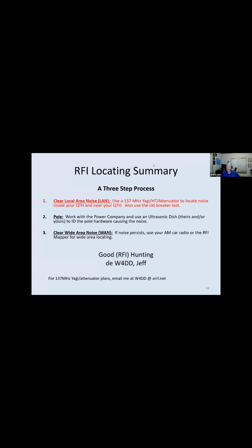Yes, it will. Whatever antenna you're using, if it's like a dipole, off the ends of the dipole would have the lesser reception. I would still say if your power lines are in the back, try and keep it as far away from those lines as possible. So maybe you want to use your house as the center support, or if you have a tree in the front yard where you can hide it effectively, use that as the center support and try and keep it away from power lines if you can.